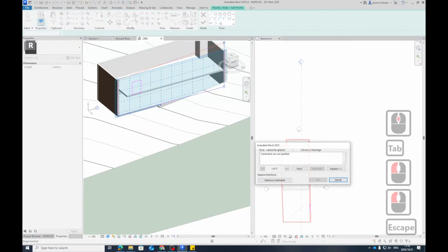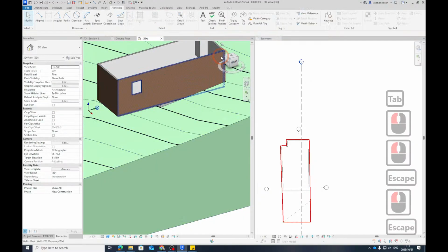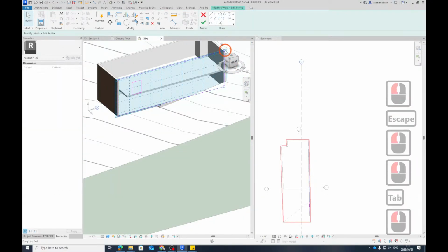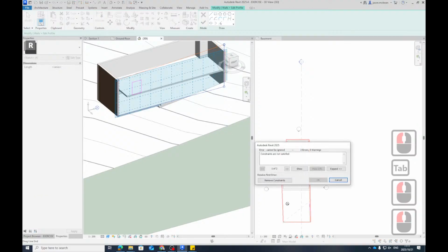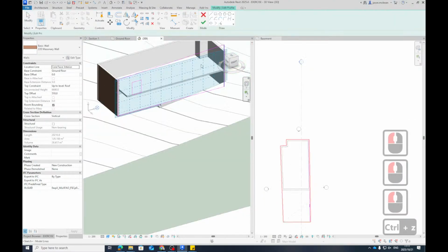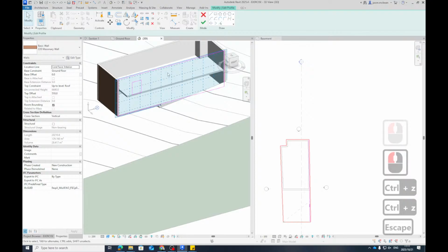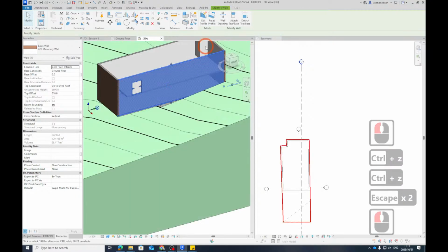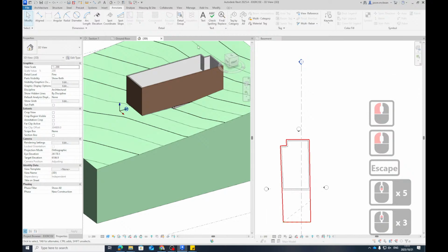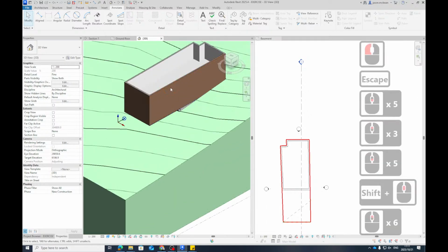I'll undo what I'm doing. You can do that as well. Sorry. Edit profile. It's typically locked for the perimeter, so you must just tell it, yes, remove constraints. You can do that, but it does cause a bit of issues. If you go and click reset profile, it removes all those holes. So there are other tools to use to do that.